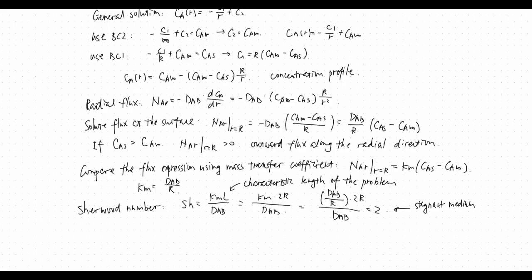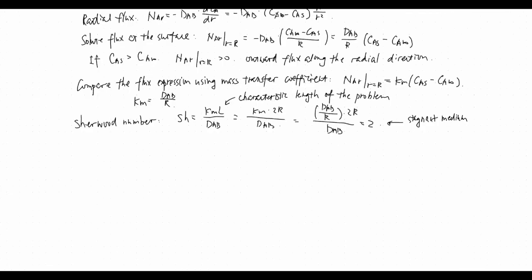You may ask, if there is a flow, so if I'm considering the case of a diffusion problem, I have a radius R, and I have an incoming flow, coming with a uniform velocity v infinity, and then I still have diffusion. In this case, it's a totally different scenario, and the stagnant result we just derived, Sherwood number equal to 2, no longer applies.